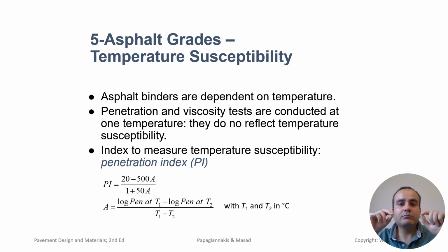The ideal binder is one that maintains consistent performance across a wide range of temperatures, providing sufficient flexibility at low temperatures to resist cracking and enough stiffness at high temperatures to resist rutting.